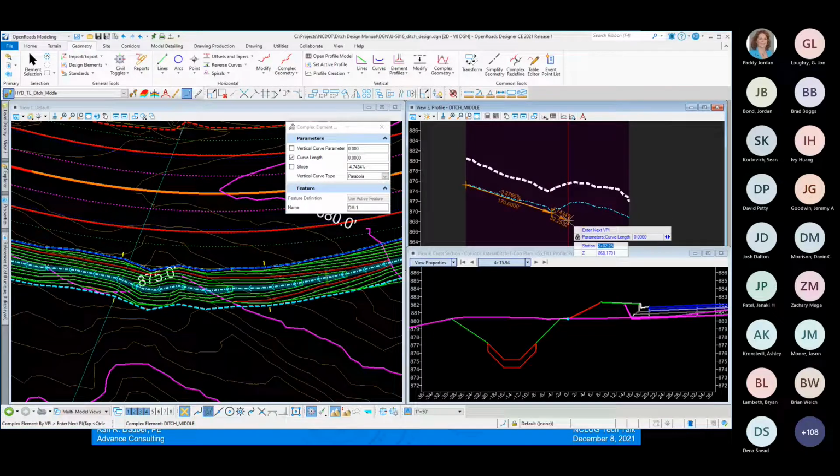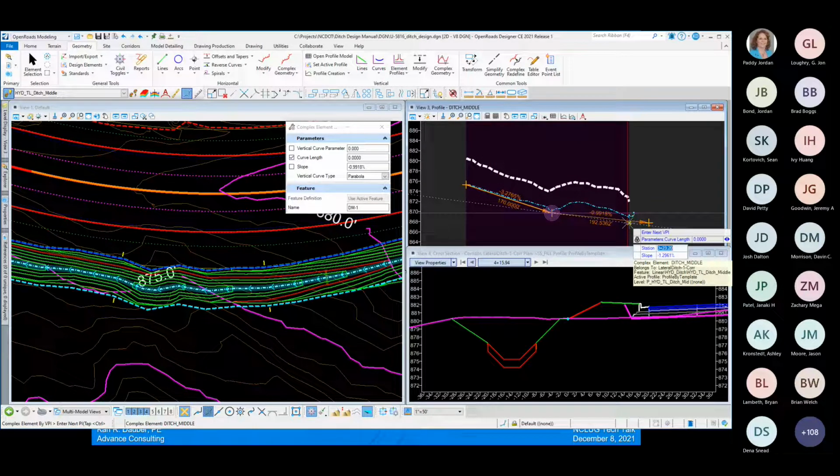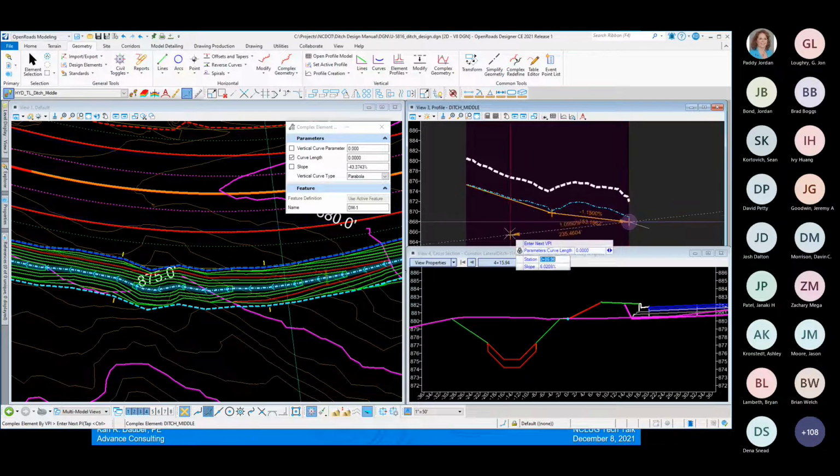So now that's my first reach. For my second reach, instead of specifying a station and elevation, I'm going to use a specified slope. So I'll change the mode from Civil AccuDraw to slope mode. Snap to the end, lock the station, and then enter in my desired slope, minus 1.15%. Lock that, data point to accept it, then reset to exit the process. I can go and turn off Civil AccuDraw now.